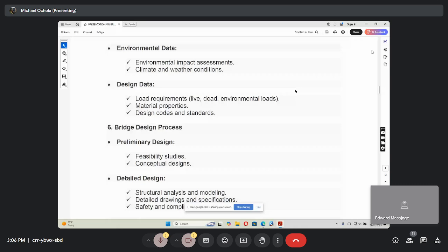But for design codes, let me also come up here quickly. We have our manual. I've given you volume 4, the bridge design manual from the ministry. It is an abstract of BS 5400, and BS, as you're aware, is already out. But there are also the latest BS EN. So you now look at that, because the abstract has loading dated as far back as 1978. That loading curve is no longer applicable. They are using the one of 2006. So if you use BD 37/01, then you get the right load. But we shall learn all those things, don't worry.